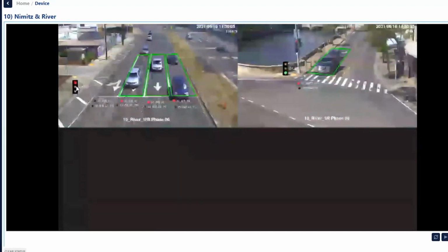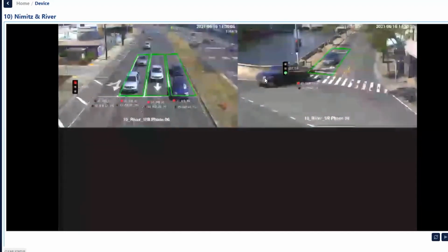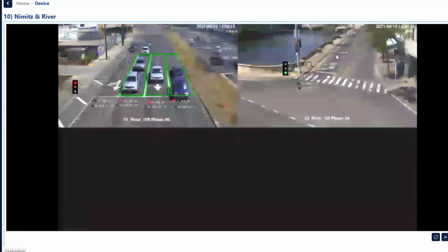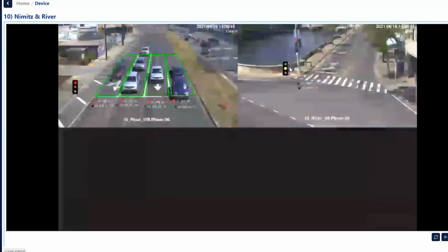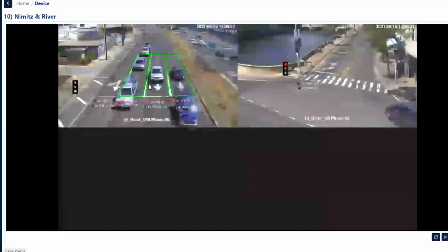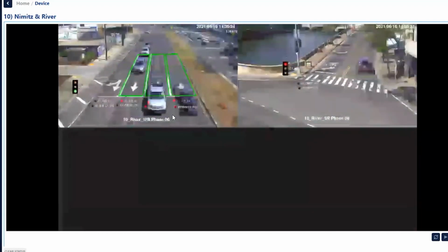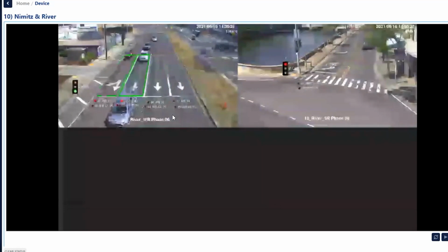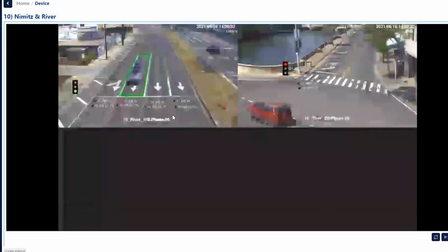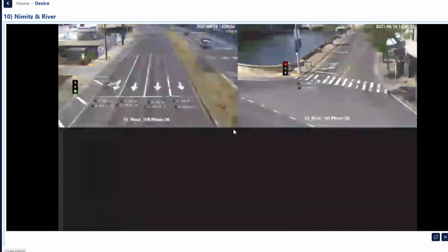So the signal turned to the red, and green signal allocate to the side street. So when the vehicle pass through the side street, sensor turn off, and then controller knows there's no vehicle waiting there anymore, so it switched back to the major street. So you can see it provides a real-time, we call actuated signal control strategy. This is the real system, so it's what happened right now. Okay. Any questions about this real video-based traffic detection system?